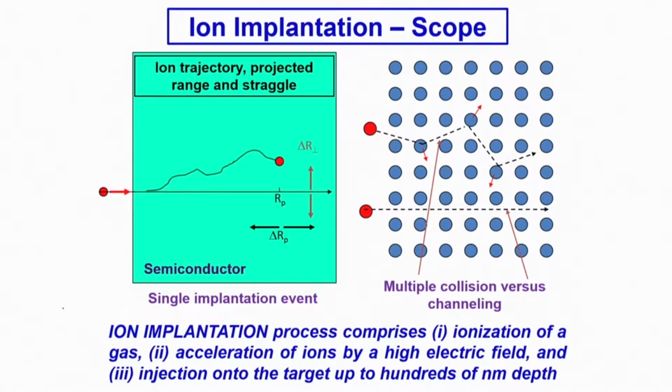But we do introduce a new set of ions or new set of species which go into the solution as solid solution, and primarily as substitutional solid solution, and in the process change either mechanical properties, structural properties, or functional properties like conductivity. So the process is ion implantation, and as the name suggests, we are talking about implanting or introducing new species ions onto the substrate surface.